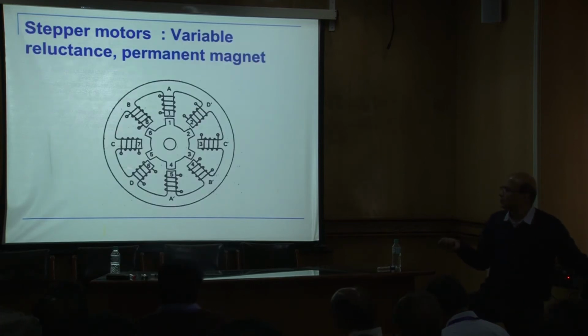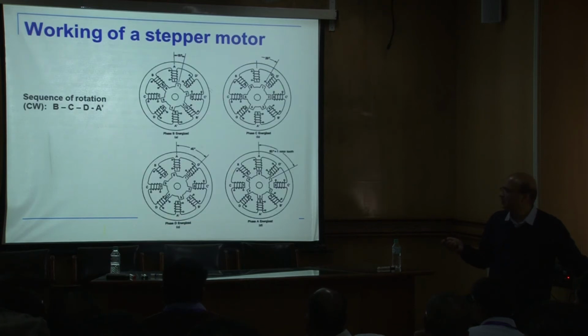So stepper motor, you would have again studied this. So essentially, it works in steps. So we have a stator and we have a rotor. So depending on how we are actuating this, so if I actuate this pole, what would happen? This fellow will get attracted by magnetic induction. Okay. So there is a permanent magnet stepper motor in which if we actuate this one, this will get attracted. Then if I actuate this one, this will get attracted. If I actuate this one, this will get attracted. Okay. So based on that, it can move in a clockwise, anti-clockwise direction simply by sequencing the activation of the pole. Okay. This also experiment we have, which you'll have to do, write a program and then use microcontroller to control.